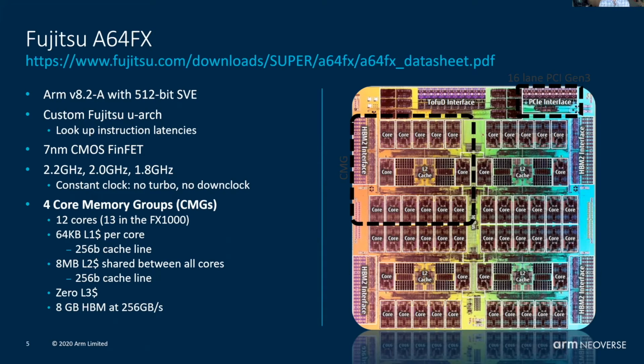And this is in part because the A64FX was co-designed for the specific applications that Riken and the Japanese computing community really care about. It really favors the types of apps that should be running on a system like Fugaku. And so that's reflected in the microarchitecture. And you see that general purpose compute, say commodity HPC workloads, require a lot of tuning to get performance out of this platform because it is optimized for a very specific design point.